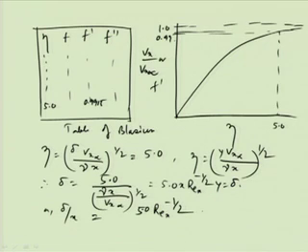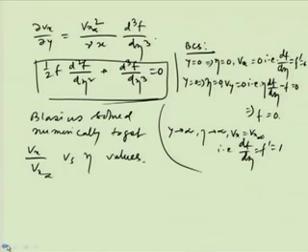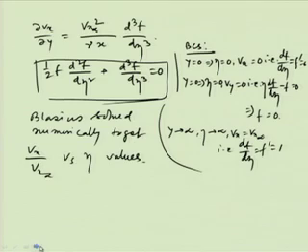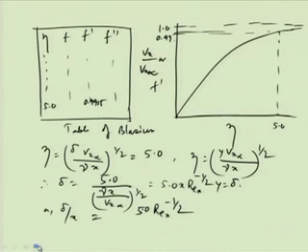Now, if we see the definition of eta, eta is equal to y by this, I am sorry. Here we will write this to the power half into delta, and y is equal to delta here. So, delta by x is equal to 5.0 into Reynolds to the power minus half.